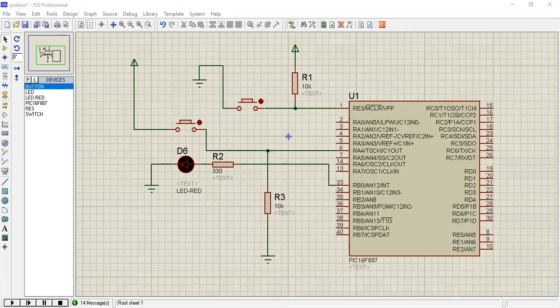So we will get 0 volts and 5 volts only. That means digital 0, 1 only. Between those values we don't get. Between 0 volts to 5 volts we don't get. We get only the values 0 volts or 5 volts. So 3.3 means it takes it as 1. 2.2 will take it as 0, because 0 to 5, that is 5 divided by 2 is 2.5, right?